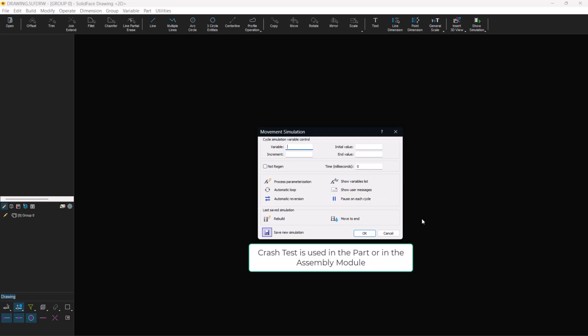Clash test. In the case of the 3D part and assembly modules, the system tests for occurrences of collisions between the faces, bodies, or components. This clash occurrence forces specific variables to receive a value different from 0. Then, logical conditions test those variables and perform the necessary tasks to handle this information.